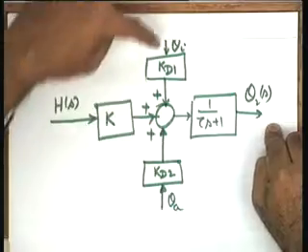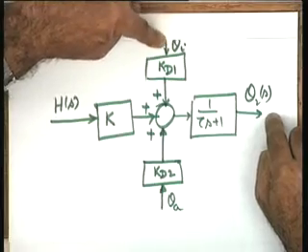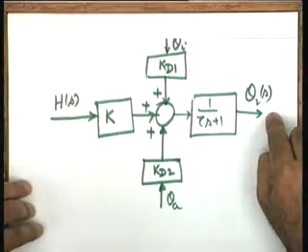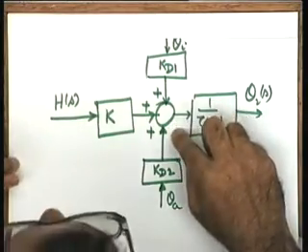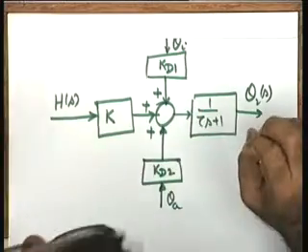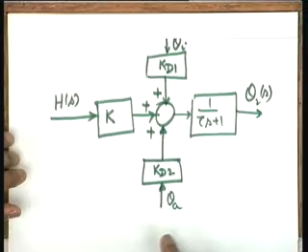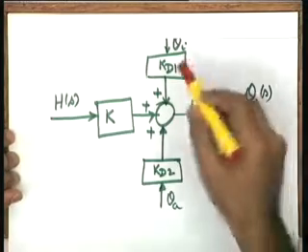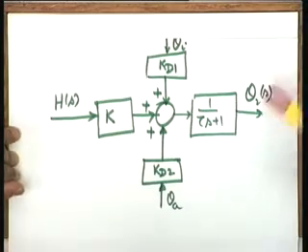This is the input output relationship. Now, from this you get between theta 2 and h, setting theta I and theta a equal to 0, naturally whatever we have written we are getting. Similarly, setting these 2 variables to 0, you have got the transfer function between theta 2 and theta I, and identically the third transfer function. So, this is my summing block. It is a symbolic representation of the additive effect which is going on in the process, and these 3 input variables in this particular block diagram have been explicitly shown, and this is the output variable theta 2.